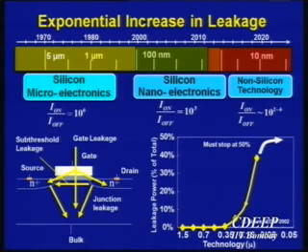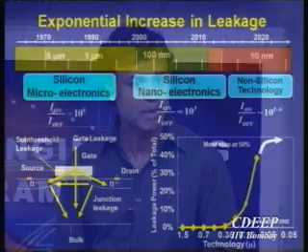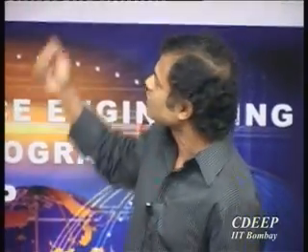And again, some of you might be familiar with it. People put patches, they do angle implants, and if this is N plus in an NMOS device, you make regions right around here of the drain where you make it P plus. So unfortunately, if you have a P plus and an N plus region, that's actually a diode, and they're reverse biased, so there can potentially be band-to-band tunneling. And due to that, again, there can be some increase in leakage current. So even though you try to take care of certain things on one side, your leakage current increases.